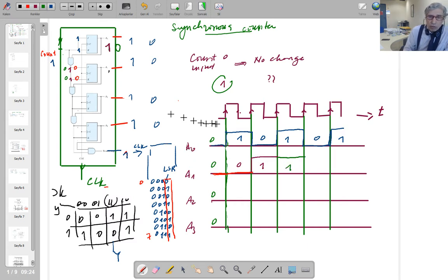So if you look at the third one, before the clock pulse, let me change the color once again. Our output is going to be 0 here, isn't it? Third clock pulse, before the... this is the fourth clock pulse, sorry. So the third program, we have done it. So at the fourth clock pulse, our A0 value is 1, not 0, but 1.